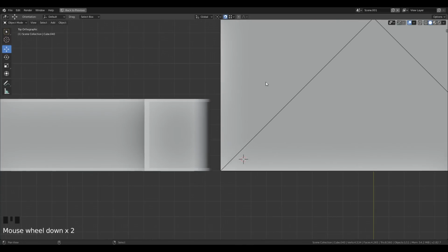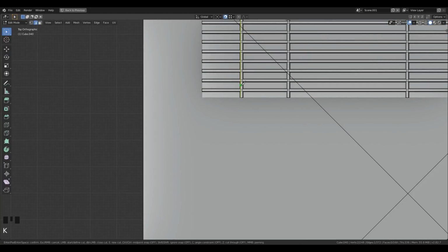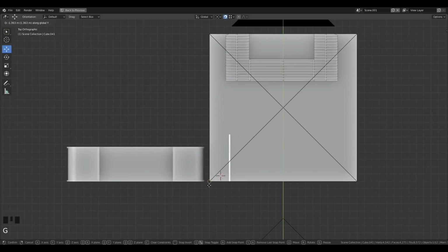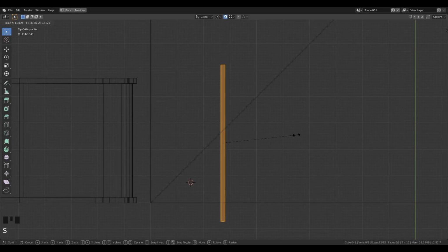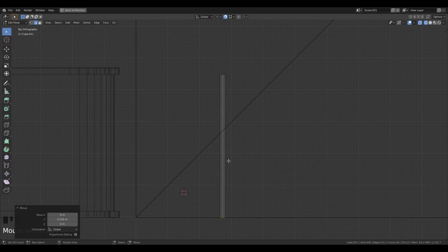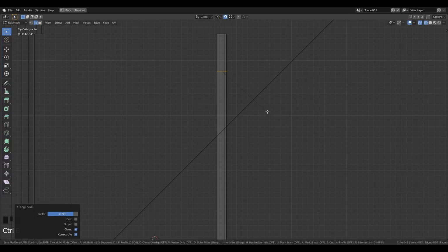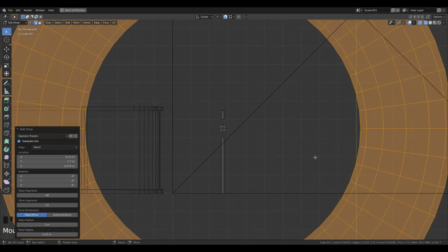To make the grill, I have used the same cube which I have used for the stairway floor. So in edit mode, duplicate it and separate it from the floor mesh. Then use the same snap tool to snap it to the bottom of the plane and then give the same height to it by using the reference mesh. Then I have added an edge loop and slid it up slightly to the top end and have beveled it and deleted it. Then select both ends and put the 3D cursor to the selection and add a torus mesh between them.